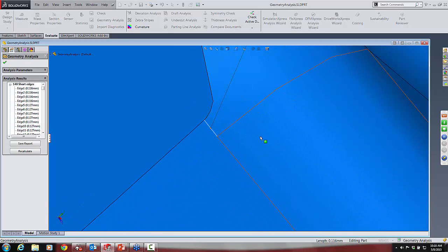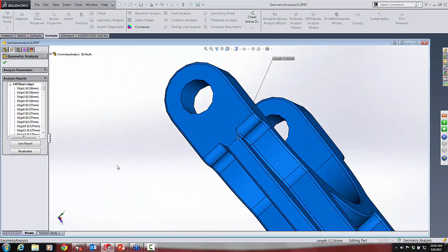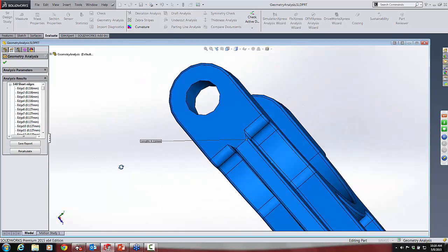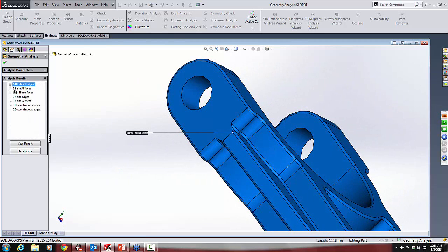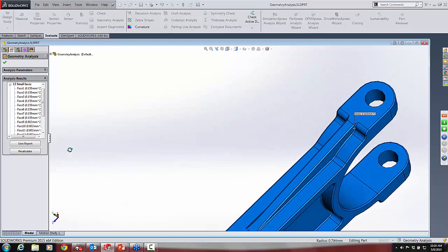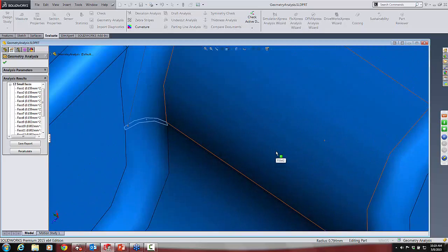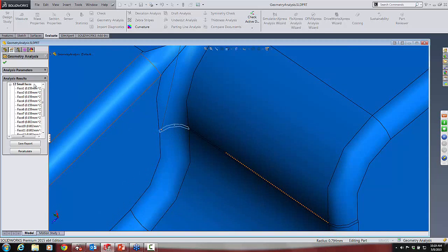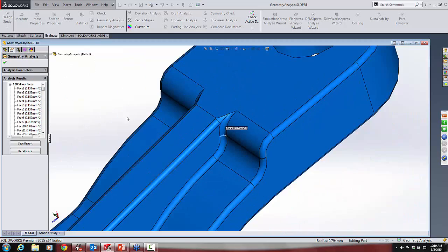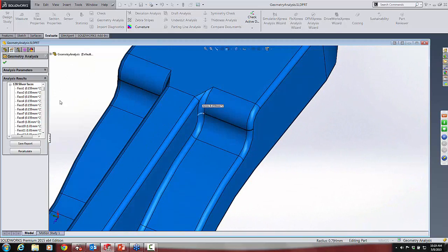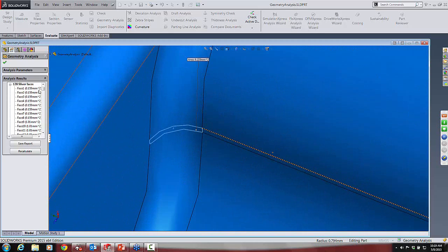And you can see with that short edge there, it'd be a pretty difficult time to try to mesh this thing with all these short edges in here. So there's our short edges, or a few of the short edges, small faces. So there's a little small face here. This, again, small faces, not just for FE analysis, but a lot of times you try to fill up something with these small faces you'll have issues with. And actually, just luckily, I picked the same face for the sliver faces.